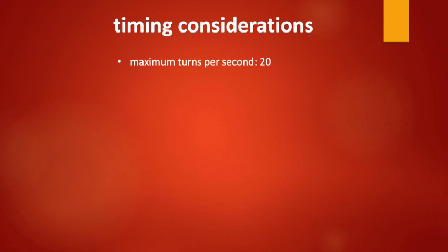The timing of the LED control is the central challenge of the rotating display. That is why I would like to shed a little more light on the control of the LEDs at the end of this video. In this calculation, I would like to assume a rotational speed of 20 revolutions per second. This corresponds to a time per revolution of 50 milliseconds.